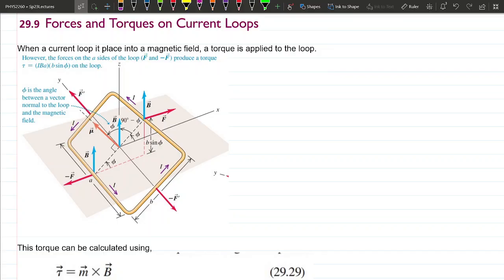These are going to be on the same axis, so it's like two forces trying to pull something on the same axis, so it's not going to rotate at all this way. It's the fact that we have an offset axis that's causing it to rotate only in this direction, and if you pull this way and this way, it doesn't rotate.